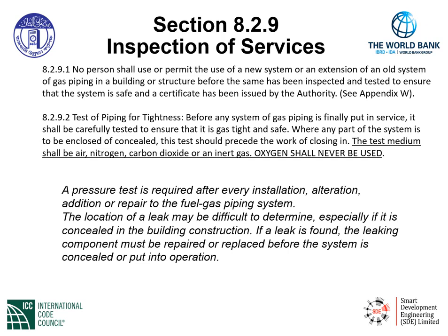The test medium shall be air, nitrogen, carbon dioxide, or an inert gas. Oxygen, of course, shall never be used because oxygen mixing with oil can produce quite an explosive effect. Pressure test is required after every installation, every alteration, every addition, or even repairs to the fuel gas piping system. We need to verify that the system is tight and leak-free.